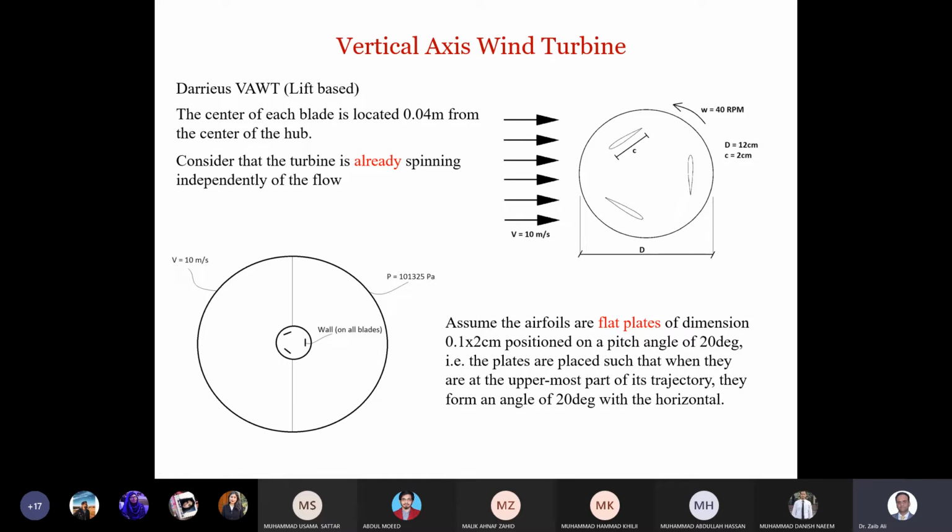For example, in internal flows or external flows, like a 3D wing, the wing was stationary and the air was flowing around. So what options do we have in Fluent to simulate moving bodies like this vertical axis wind turbine, where the blades are rotating?